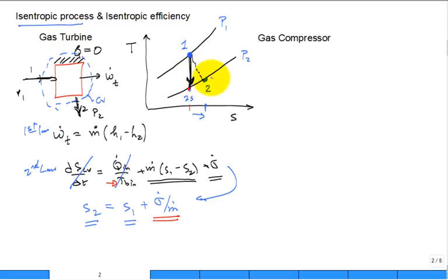Why do they put a solid line? Because it's an indication that the process is internally reversible along that path. Why do they put a dashed line? Because it is an indication that it's not internally reversible. Remember this equation, Q equal to integral T ds. On a TS diagram, the area under the curve is an indication of the amount of heat transfer. You look at this and you go, hey, I can see the area under the curve, but it's not internally reversible. That's why they put a dashed line. Don't visually interpret the area under that curve as the amount of heat transfer.